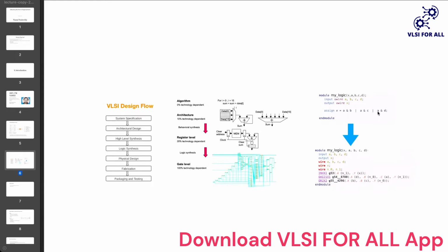This is written using an HDL, or a hardware description language. Generally, people use Verilog, VHDL, or SystemVerilog. After your logical synthesis is done, it is converted into the format you see below, where you still have the module. Basically, all the AND functions or the OR functions are converted into the equivalent gates.